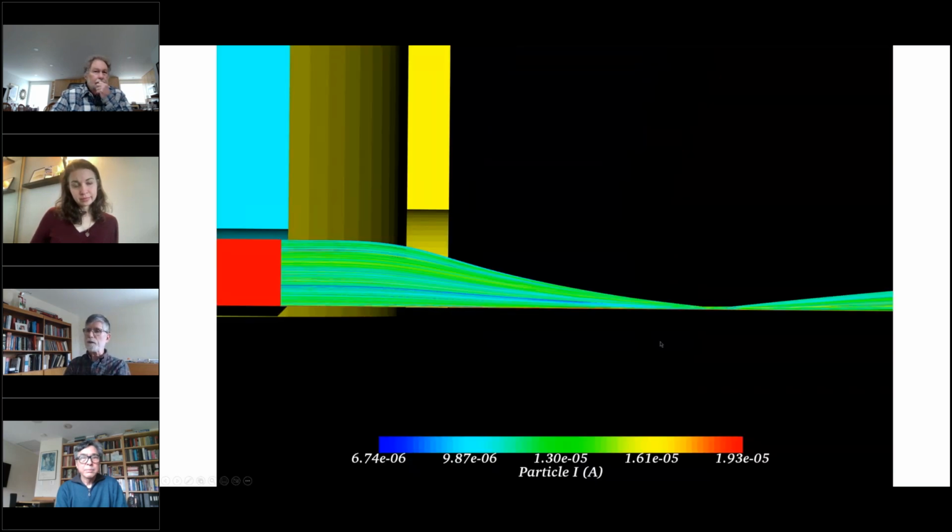First I show you the result, because what we have here is a beam that starts out quite large and then comes to a small focal point. This is typical in X-ray tubes. If you had to mesh this whole problem so that you had at least 4 or 5, and preferably maybe 10, meshes across the beam at its smallest point, then you would have a huge problem.